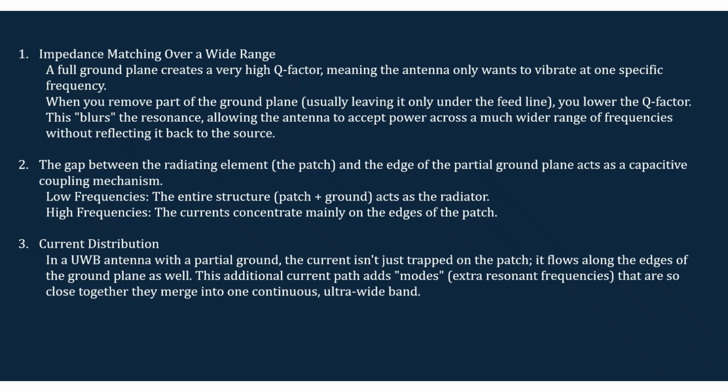We can also see that the current is not only below the patch, but is also distributed on the partial ground plane. This also gives rise to the wideband response. That's why we are getting an ultra wideband response when we are using a partial ground plane.